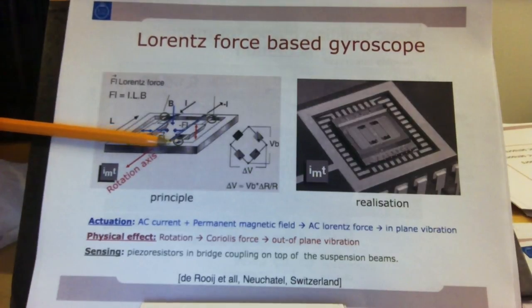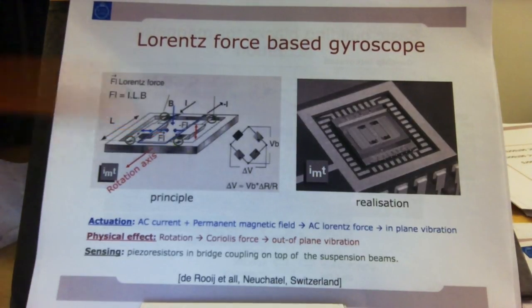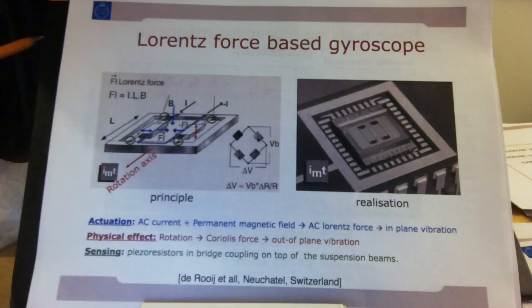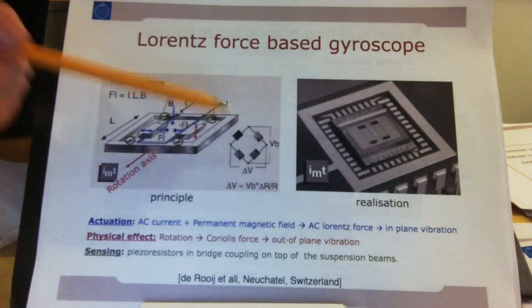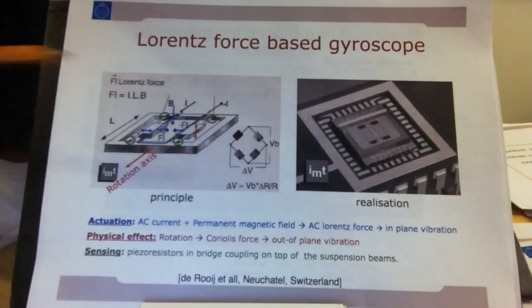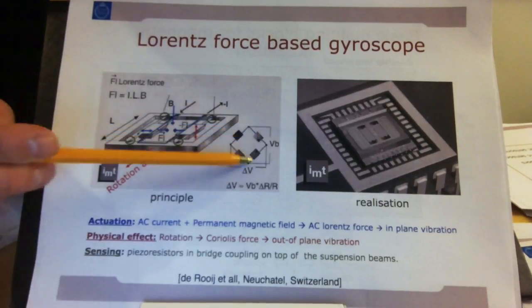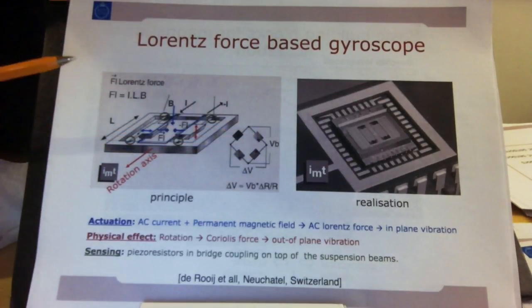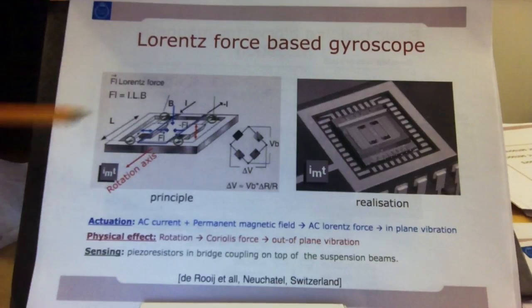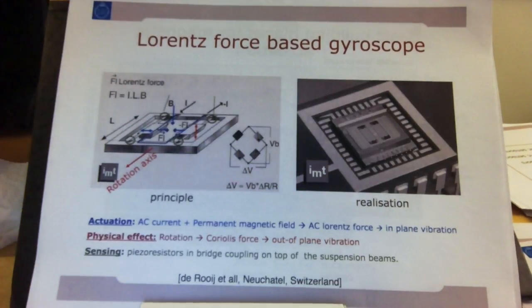Strain gauges are piezoresistors and are of course temperature dependent. So the structure is temperature dependent. However, we've put it in a Wheatstone bridge, and if we do that correctly, as I've explained, the Wheatstone bridge will help you to cancel out the temperature sensitivity. So in total, the system will not be temperature sensitive.